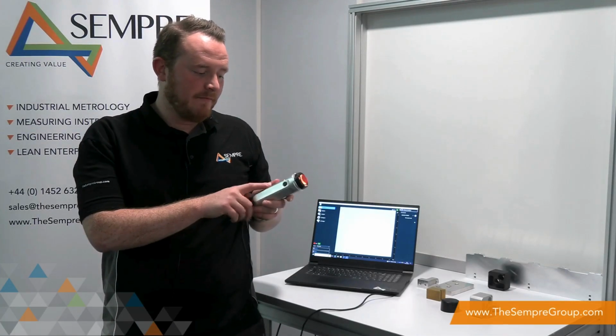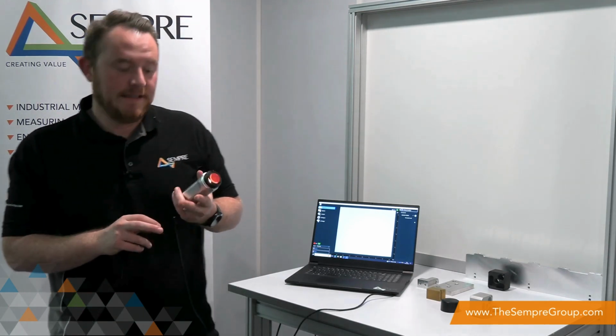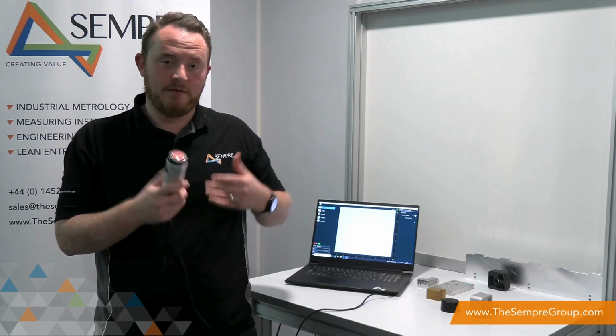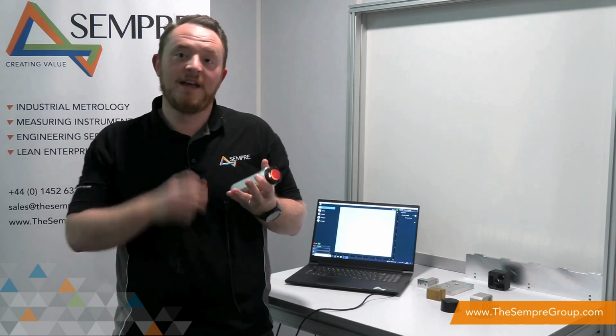So here we have the GelSight Mobile Series 2 system. The GelSight is used to characterize surfaces, whether that be a surface defect, surface roughness, a radius, a chamfer, a break edge, or hole diameter. The system is used to characterize those kinds of features and give us a report or a template to capture that information so that we've got traceable data to suit the current industry standards within aerospace, automotive and high precision